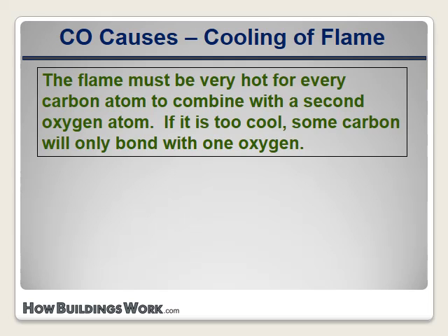The third scenario that can cause carbon monoxide to be generated is a flame that's too cool. Quite a bit of energy must be available to create the bond between a carbon atom and a second oxygen atom to form carbon dioxide. If there's not enough heat, then the reaction will stop with some of the carbon only bound to one oxygen.